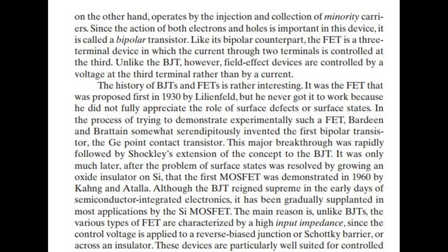It was the FET that was proposed first in 1930 by Lilienfeld, but he never got it to work because he did not fully appreciate the role of surface defects or surface states. In the process of trying to demonstrate experimentally such a FET, Bardeen and Brattain somewhat serendipitously invented the first bipolar transistor, the germanium point contact transistor. This major breakthrough was rapidly followed by Shockley's extension of the concept to the BJT.